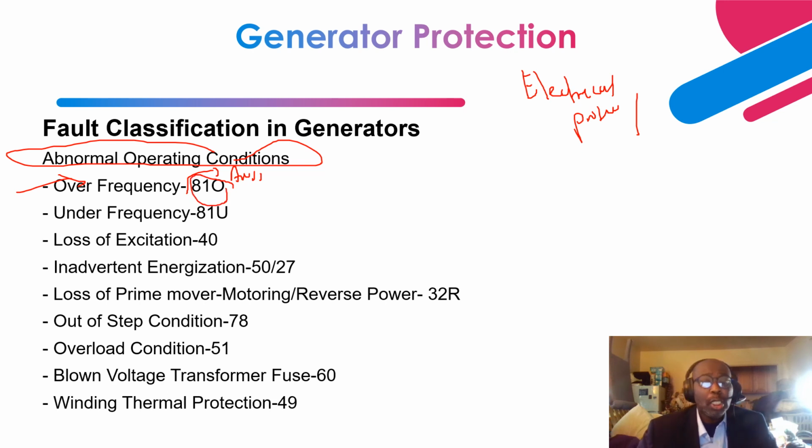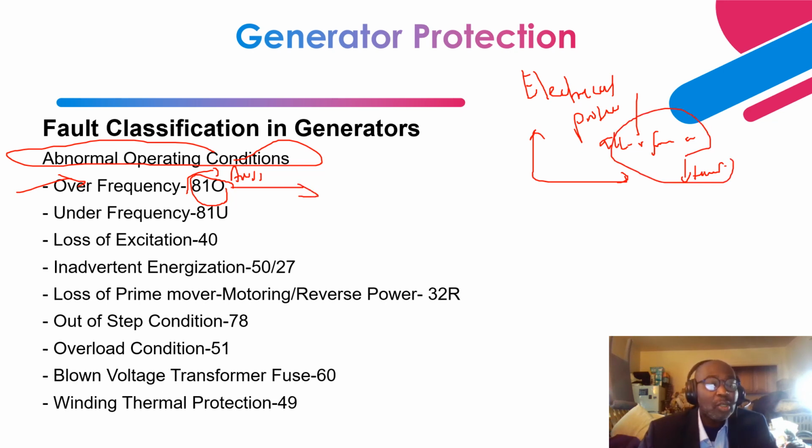The turbine generator manufacturer provides the protection relay engineer charts that say this is the allowable, permissible over frequency that you can operate at, based on a time duration. So this is what the protection relay engineer utilizes to set this over frequency.